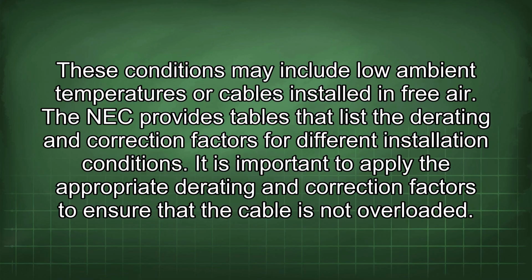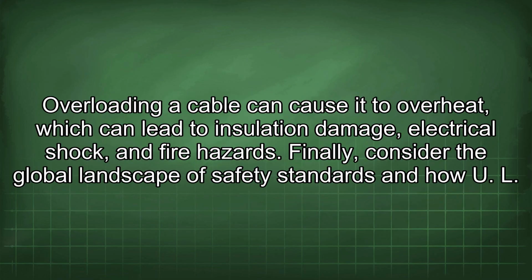The NEC provides tables that list the derating and correction factors for different installation conditions. It is important to apply the appropriate derating and correction factors to ensure that the cable is not overloaded. Overloading a cable can cause it to overheat, which can lead to insulation damage, electrical shock, and fire hazards.